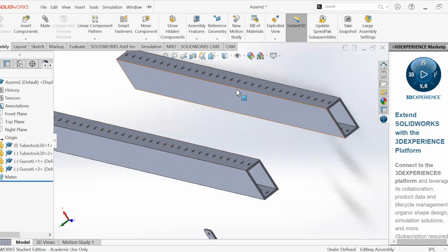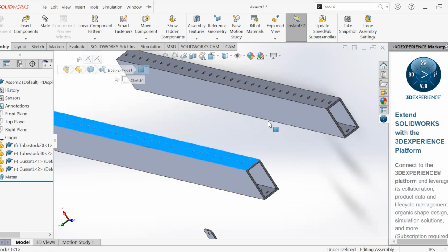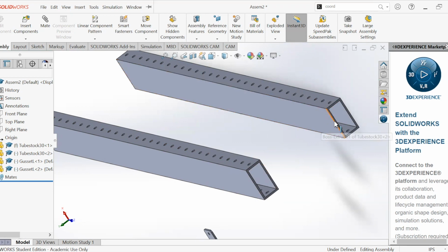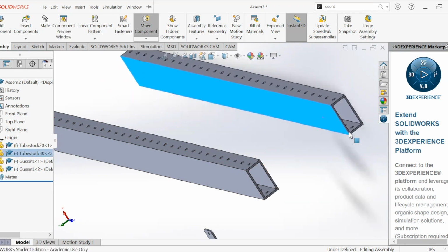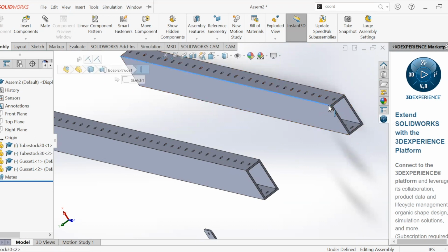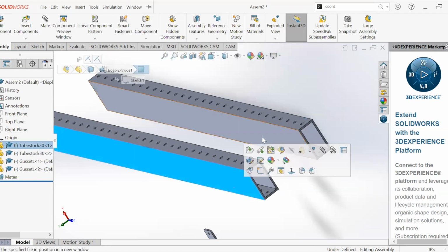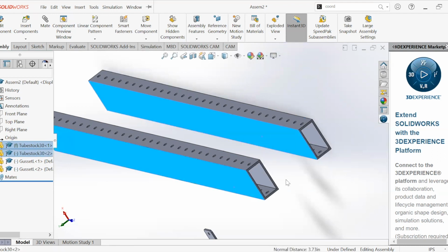Oh, and that plane itself can't move. So everything else can move across that plane. But since the planes are fixed together, nothing can move there. Since we attach this face and this face as well, this can no longer move in the direction of this line. So it can't move there and back. Rather, it can just move forward and back since there currently isn't anything that's restricting these faces.